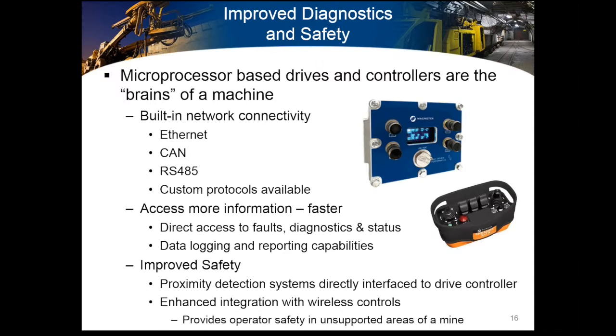Lastly, we'll look a little bit at some of the diagnostics and benefits of a drive. Generally, the newer inverters today have microprocessors, a lot of brain power within the drive itself. In the ideal situation, you want to be able to connect the drive up to other devices and be able to share information. Generally speaking, drives today have built-in connectivity to a variety of networks: CAN, Ethernet, typical RS-485, or even custom protocols.